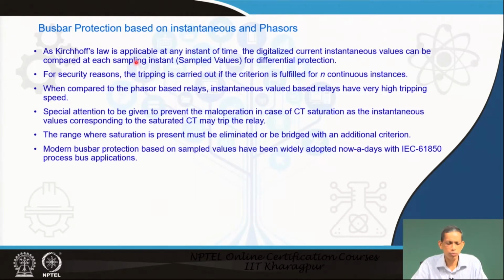Here sample values are used, but to ensure that the fault is internal to the system, n continuous instances are checked to confirm the consistency of the decision. When compared with the phasor based approach, the instantaneous approach will have high tripping speed, obviously. Special attention must be given to CT saturation detection. For an external fault with CT saturation, still the differential current will be significant.